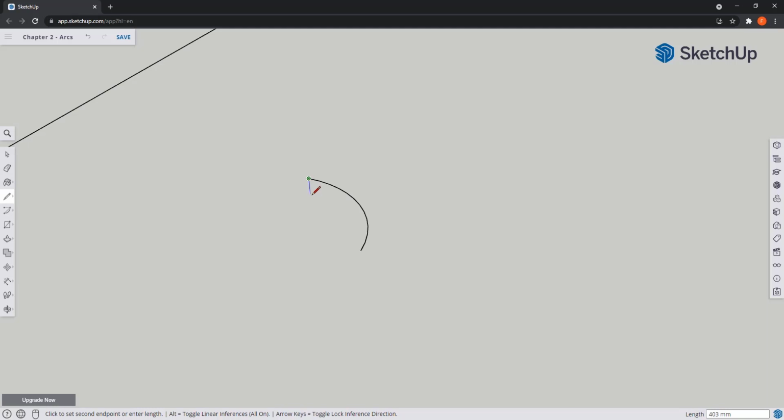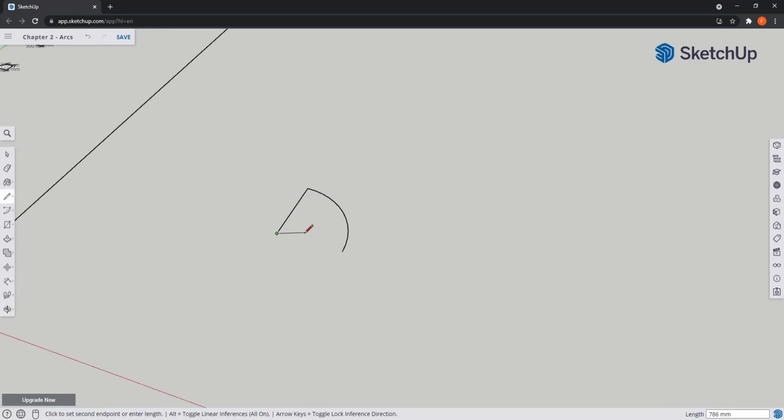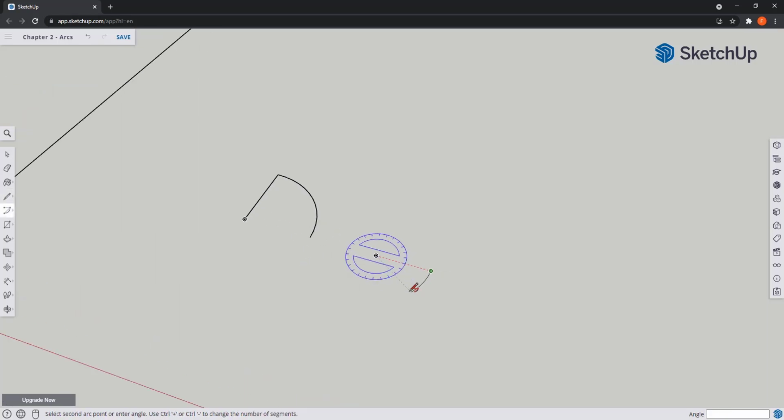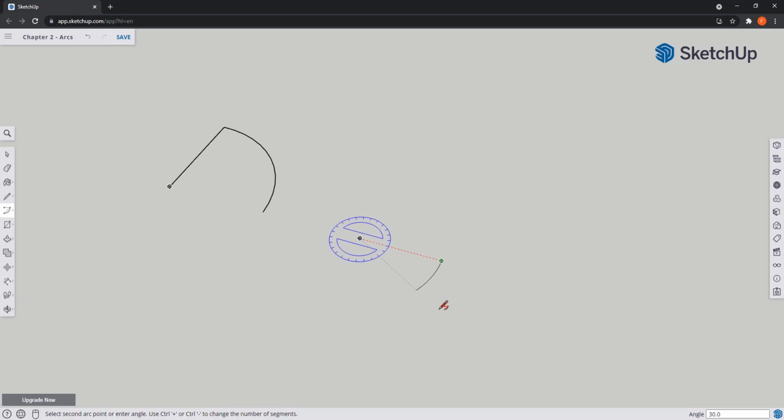And then I'm going to draw a line from there until the center, using that inference point. And as you can see, this could be a perspective of a door in a floor plan. Then, if I want to connect the points below with a line, it creates a face automatically. Important note: when I type the angle, it's along the direction where my pointer is. Even if I am drawing clockwise right now, I need to type a positive number, this time 30.